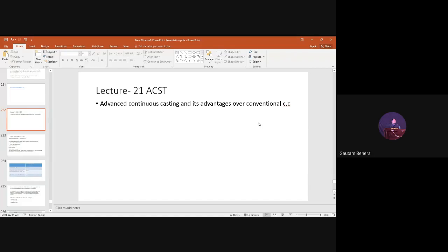A car manufacturing industry basically needs sheet or strip, steel sheet. This steel sheet has a dimension, and if I'm talking about the thickness, which is very important, it basically starts from 0.77 mm to about 3 to 3.5 mm, or 3.3 mm. So this is the range.